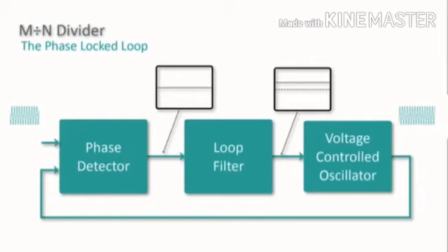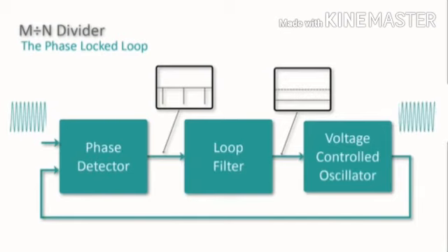Now consider the case where the input frequency begins to fall. Now the phase detector begins generating negative pulses that are rectified by the loop filter to create a negative DC level. That forces the VCO to run more slowly until, once again, the input frequency and the VCO are in phase and matched in frequency. Now the system is still stable and the loop is still locked.